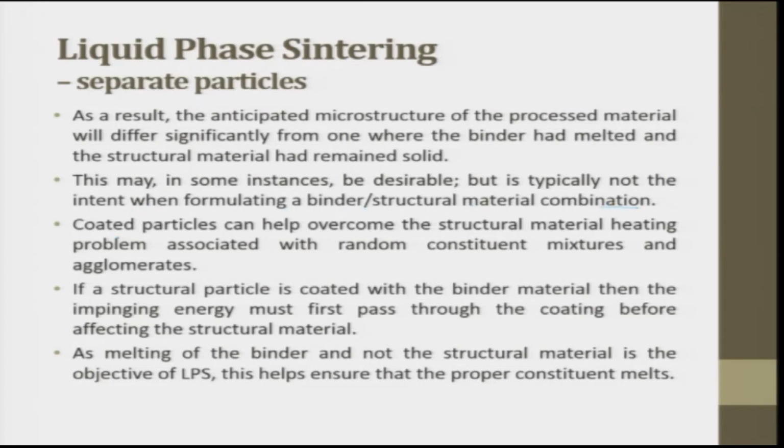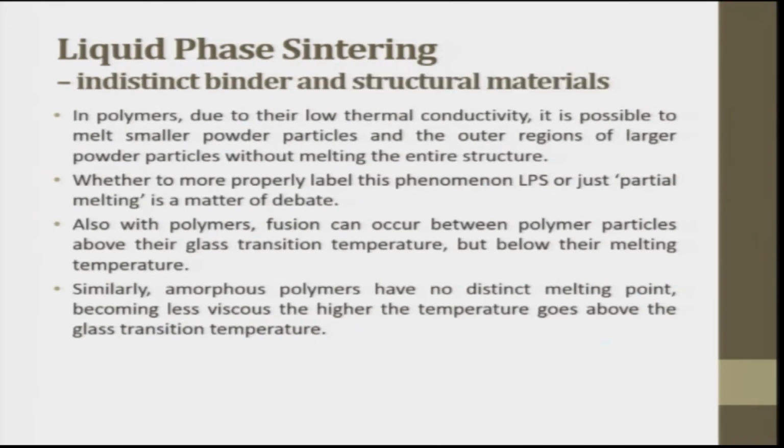The coated particles can help overcome the structural material heating problem associated with the random constituent mixing and agglomeration. If the structural particle is coated with a binder material, then the impinging energy must first pass through the coating before affecting the structural material. As melting of the binder and not the structural material is the objective of LPS, this helps to ensure that the proper constituent melting happens. So, the last part of the powder is distinct binder and structural material.